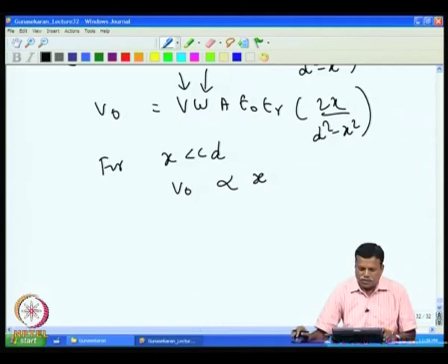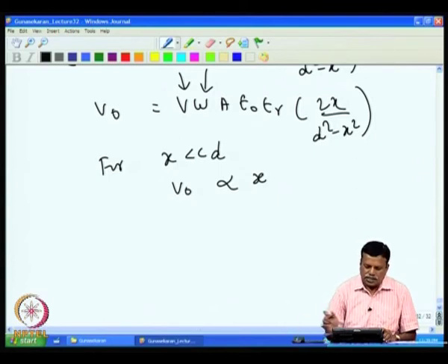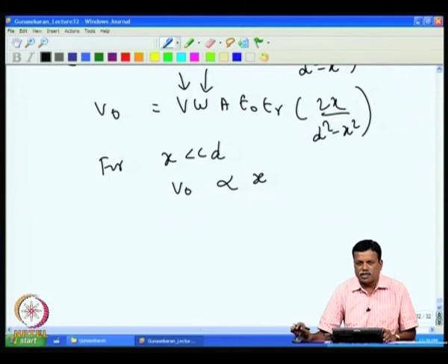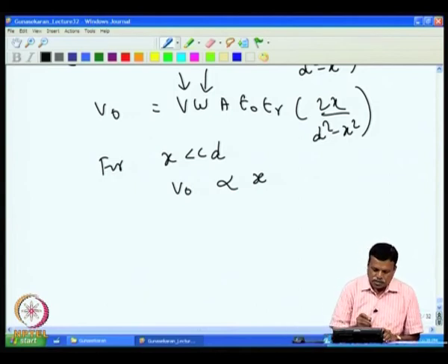linear? Now, one possibility is if we go for area variation, then this circuit appears to be linear. So, let us see what happens if I use the displacement measurement using area variation. Suppose I arrange the capacitor in such a way that for a given displacement, the common area occupied by the two plates varies, then we see what happens. So, area variation.